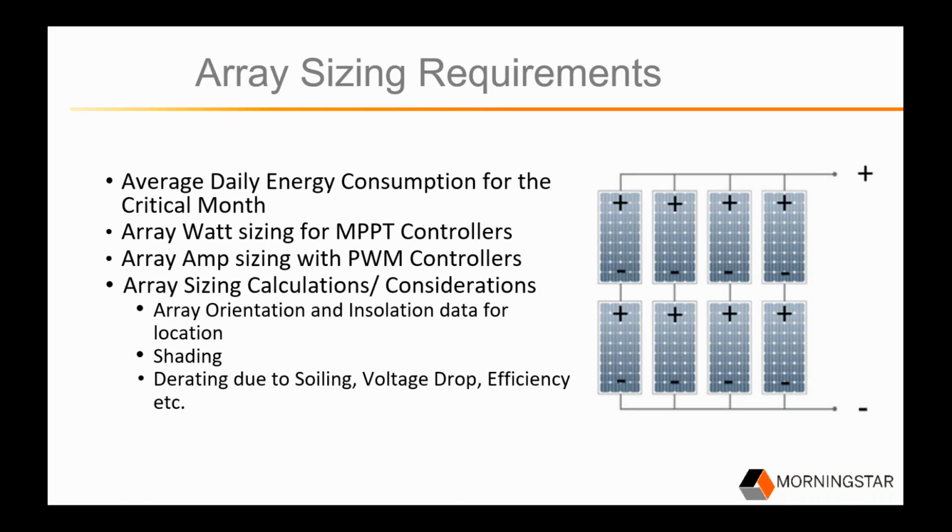We're not going to discuss all the details about how the array size is calculated, as it's beyond the scope of this presentation, but one of our distributors can certainly help you with your array sizing so you can determine the number of modules at a given power rating required for your system. From there, you can choose module brands and their specs to input into the string calculator in order to see optimal series and parallel string configurations and related notes.